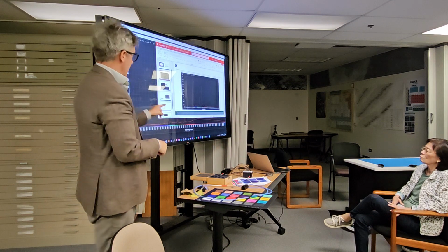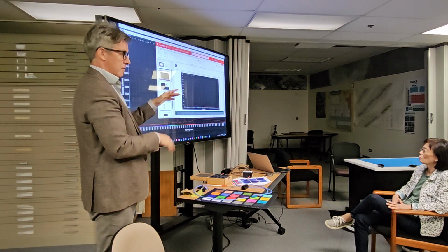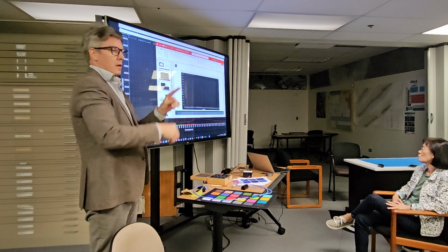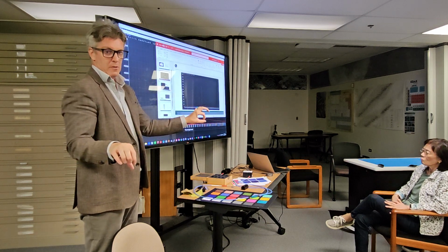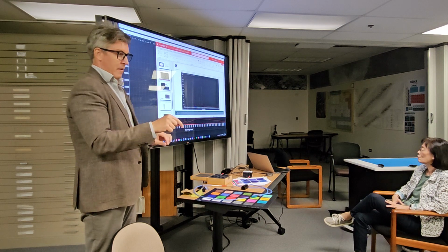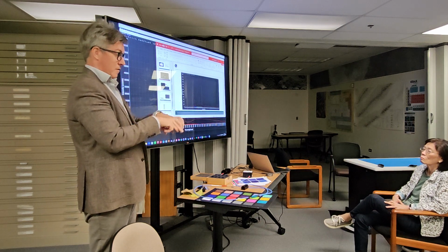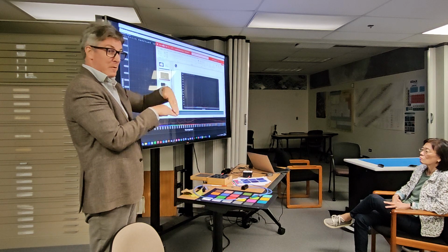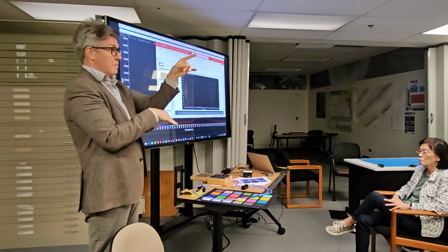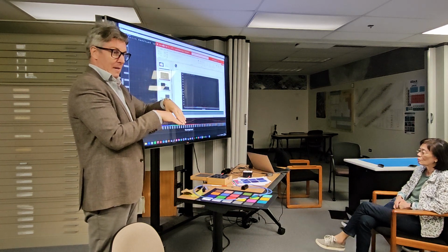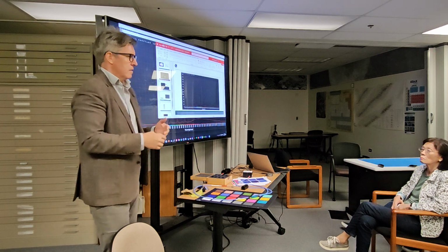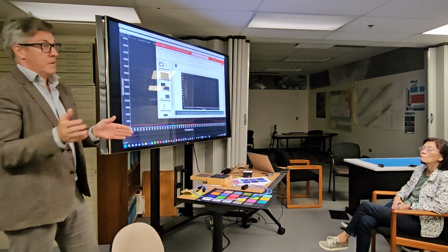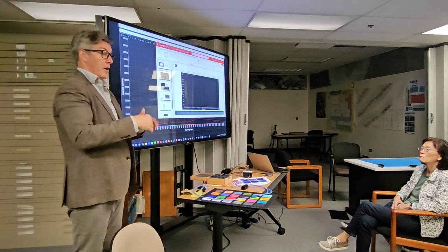So the tungsten element causes excitations in mercury at a wavelength we cannot see. Those photons strike what they call the phosphor, these rare earth metals that are painted on the inside of the tube. When you get this down, you'll see the tube looks white, and what you're seeing is these metals painted on the inside. Those UV photons excite electrons to jump away from where they normally reside in those metals. When they relax back down, they emit photons of visible light, and that's how we generate light. And it's called fluorescence because the re-emission takes place instantly, but at a longer wavelength.